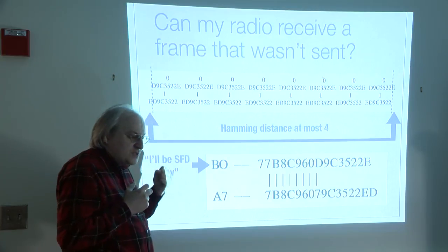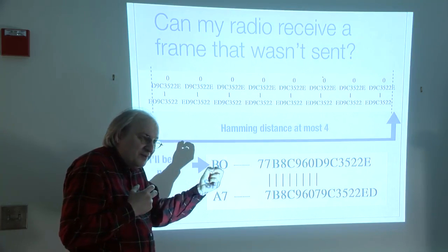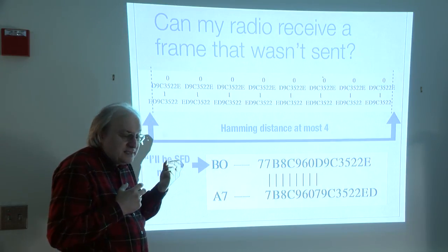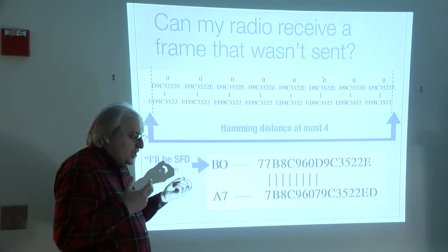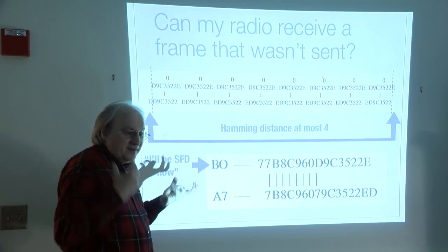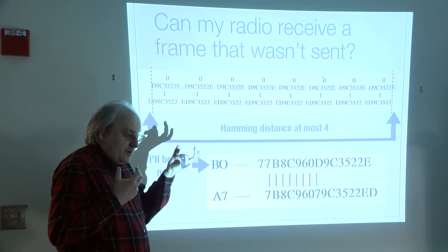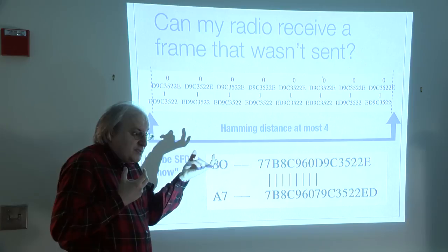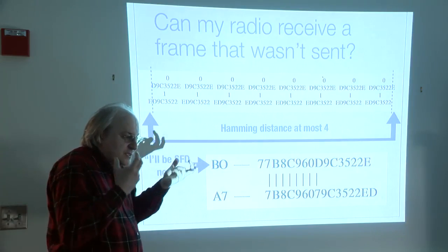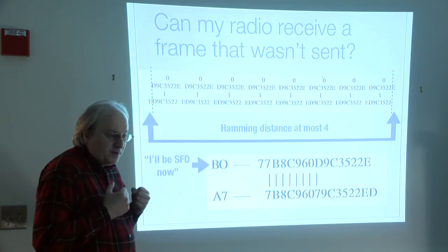There is nothing to separate the chips of one nibble from the chips of another nibble. There is nothing to separate the bytes from each other. They are just artifacts of parsing, because this is exactly what the digital radio chip does to this stream. It extracts boundaries out of it. Everything else in the stack depends on those boundaries.